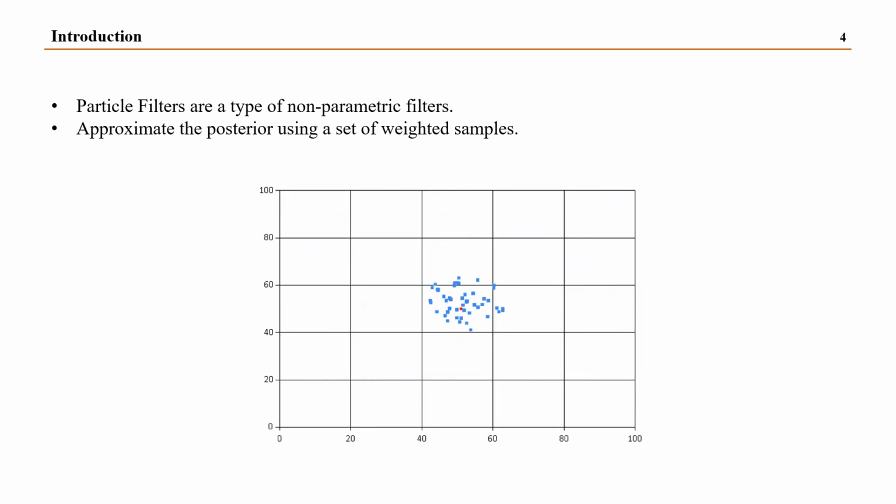Now the following figure might show how a typical particle filter works. You can see that at the beginning of the localization, the particles are spread out, then they focus on the robot position as it progresses and incorporates more measurements into the sensing range of the robot.